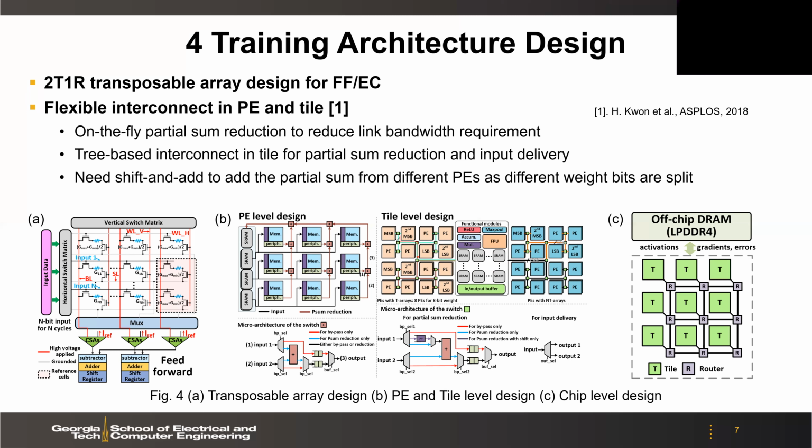There are also special function units such as ReLU and max pool in each tile. As the hardware resources assignment protocol may assign a different number of processing elements to each layer, a flexible interconnect design strategy is utilized for the processing elements and the tile level communication.